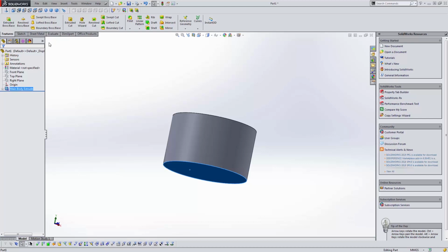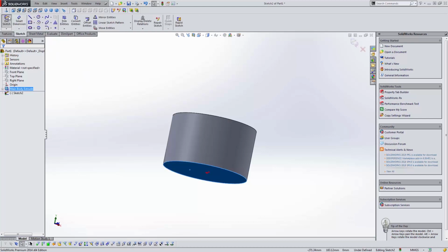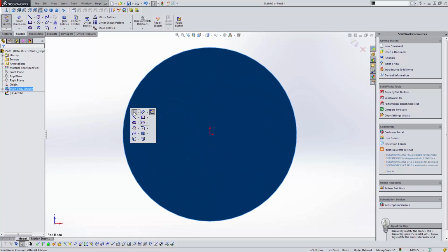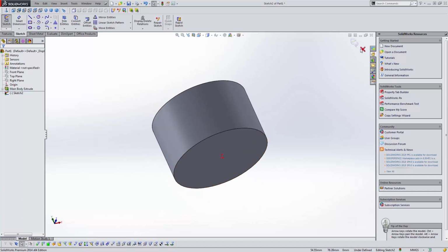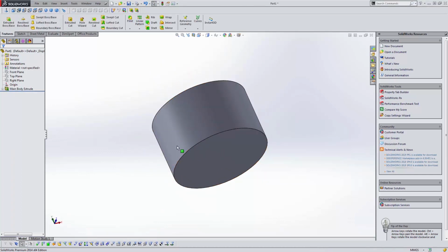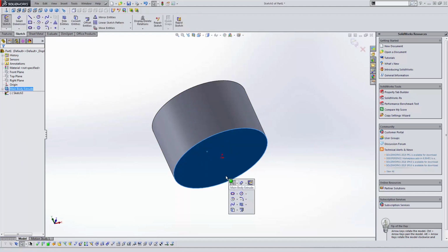So the next step, what I want to do is extrude another circle on this face. Let me go a little slower real quick. So I pick the face I want to work on, and I'm just going to hit extrude. Another shortcut for me is S, and it brings up my sketch tools. I'm going to use a circle, which is set to snap to the center. You can also use a perimeter circle.